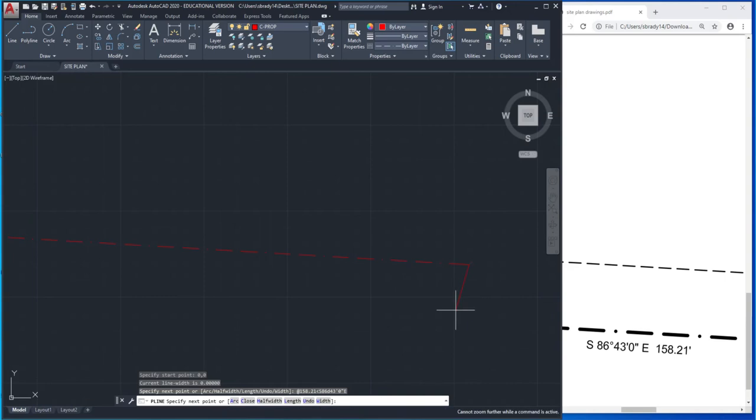This is always my good illustration of how to deal with a limit, but sometimes you'll get that, okay, where there is space over there, okay? But essentially what you need to do is hit escape and zoom extents, and then that will clear out that constraint of that limit that's happening on the one side, okay? But I was able to zoom out, right? I'm panning, holding the middle roller down, moving over, zooming out a little, panning back over to see my endpoint. And that looks good.